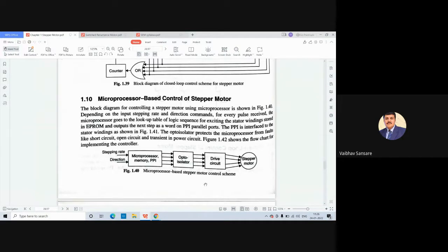And whenever a fault takes place on the power circuit of any control scheme, and if no electrical isolation is provided between control and power circuits, then these faults which take place on the power circuit lead to an increase in values of currents and voltages associated with control circuits, because control circuits are generally operated under lower value voltages and currents.